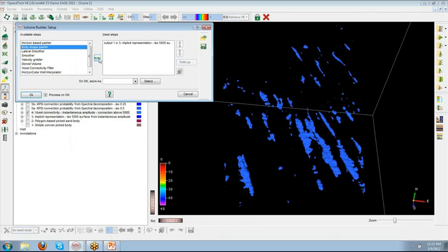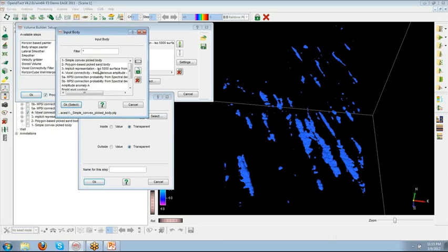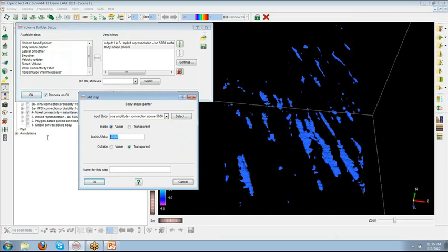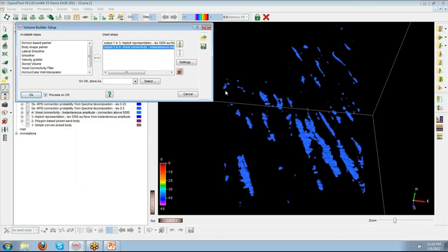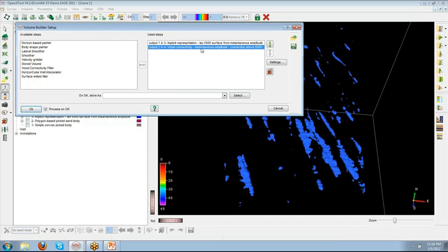If you want to output several bodies at the same time, and if they are not overlapping, you may create a flow and select multiple bodies, and here I would put another value in this second body. So then these will be two steps, and you have to remember that the steps will be taken consecutively, which means that if there is any overlap, the last step will always overwrite at a given sample the output of the previous steps.